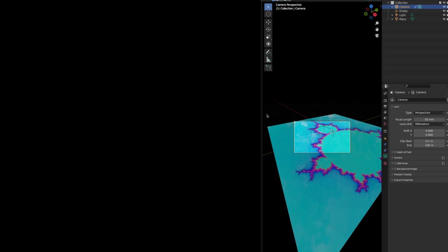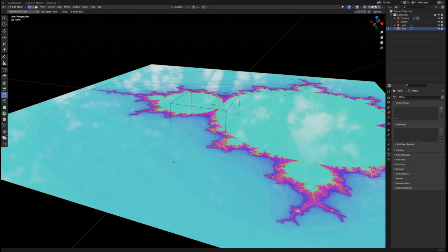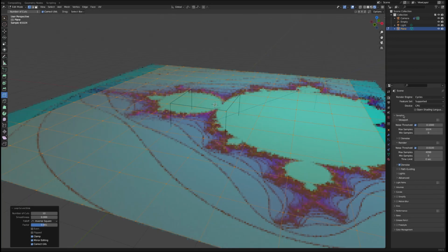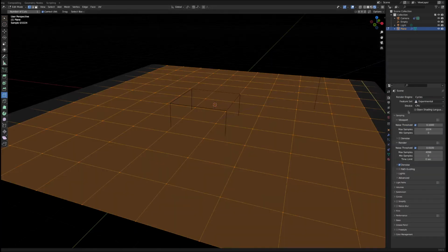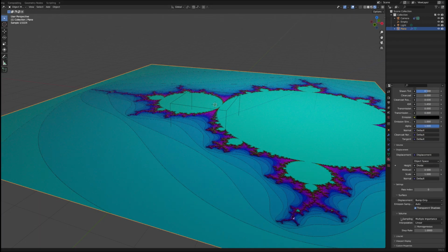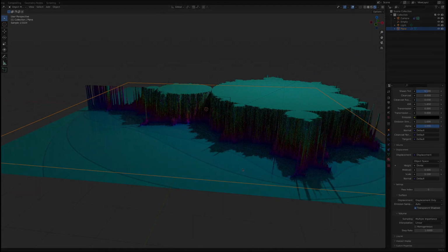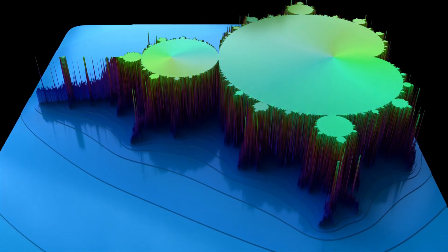But since we've come so far, let's create one of my favorite representations of the Mandelbrot set. The plane is endowed with a few loop cuts that create a mesh of 100 little squares. This mesh is refined by a subdivision modifier. We turn on the experimental settings of Blender, and then we can choose the option of adaptive subdivision. Finally, the displacement information is turned from bumps into actual displacements. It takes a second or two, but then the Cycles renderer converts the information about the number of iterations into actual heights and a nice three-dimensional Mandelbrot set appears.